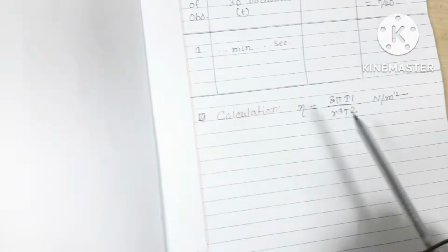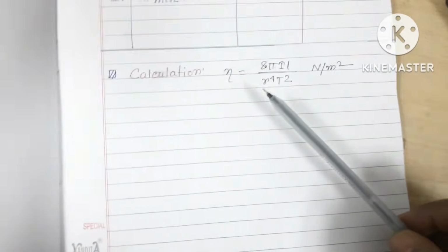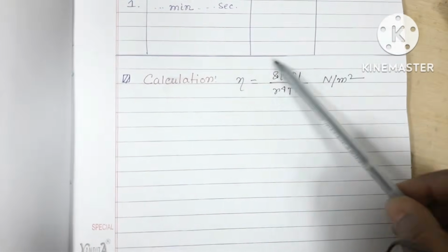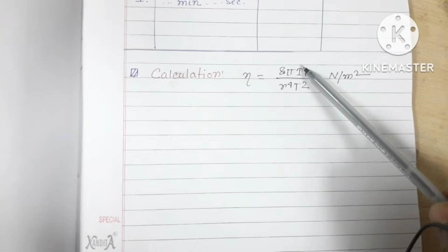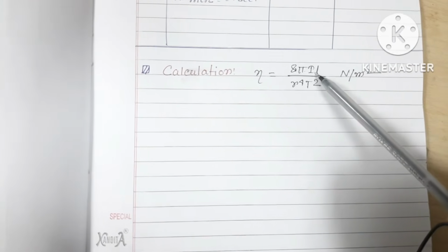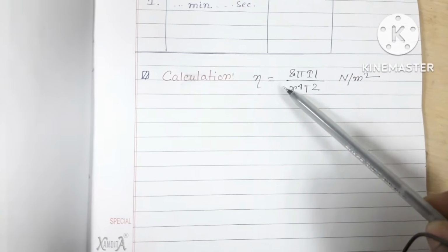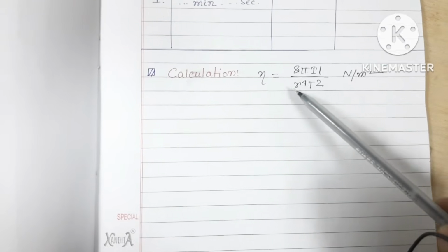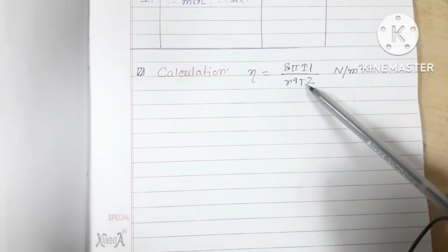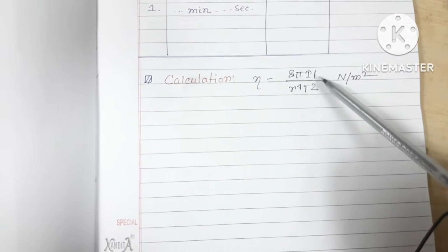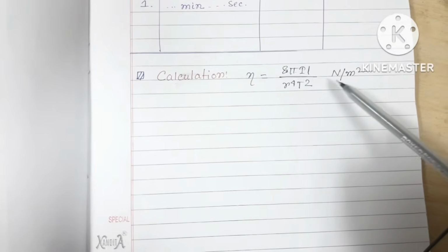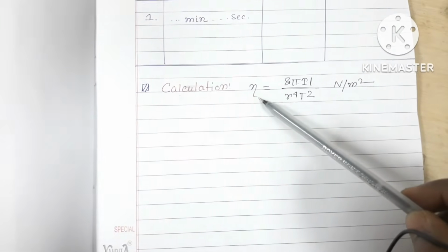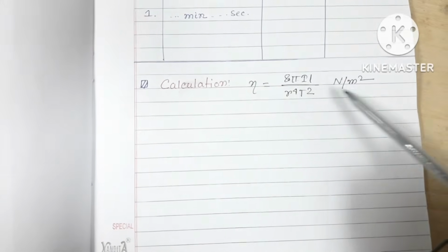So now let's take a look at your working formula. We have the I, that is half m r square, we have the small l, we have capital R to the 4, and right now we have calculated also the T. If we put in all those experimental values, you can calculate the rigidity modulus of the wire in Newton per meter square.